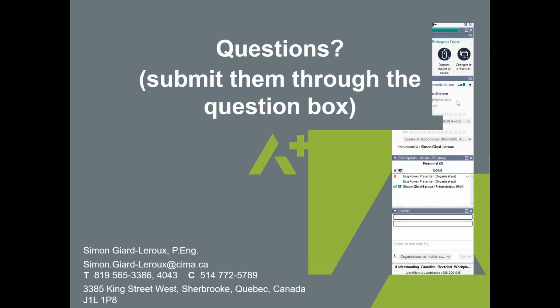The second question I have is from Kresta Zumel. If a protective equipment has a maintenance mode, do we calculate the incident energy using the maintenance mode settings? So in this case, what I've done in the past mostly was I calculated the incident energy with the maintenance mode off, created a label for this, and then calculated the incident energy with the maintenance mode on. And then this gives you two different labels for the same equipment, one with the maintenance switch off and one for it on.